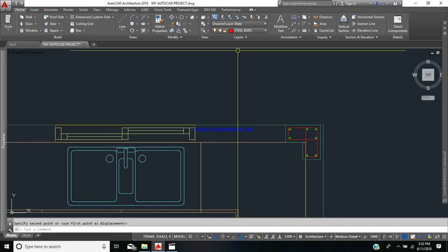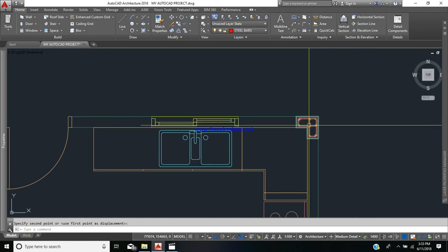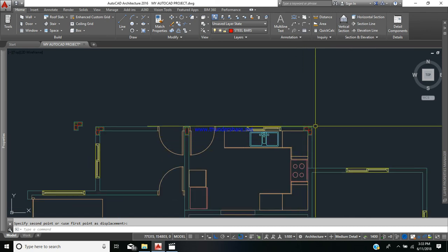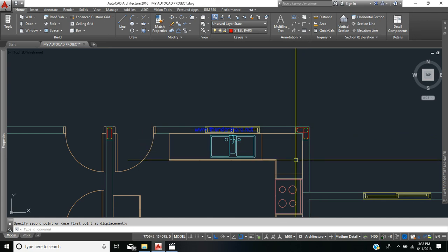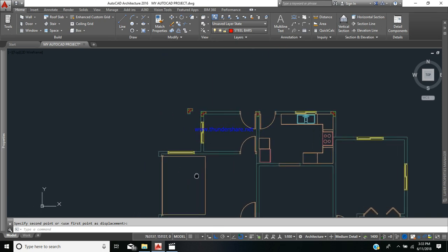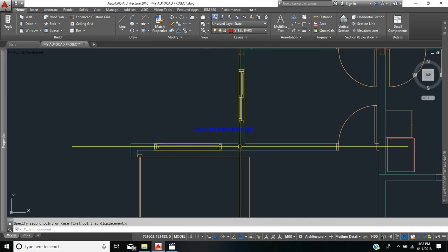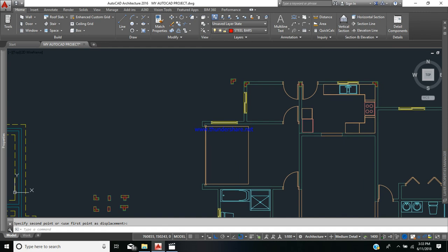I seem to have missed my point, so let me go again, and I'm going to be moving it, holding here and pasting here. That's the beauty about having your stiffeners being a block, because if they are incorrectly placed, selection of them can be easily done. Alright. For placement of, for example, a T stiffener, if you'd like, a T stiffener could have been placed perhaps here. And so again, I'm just going to be making one last placement.